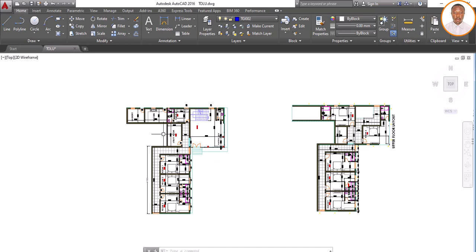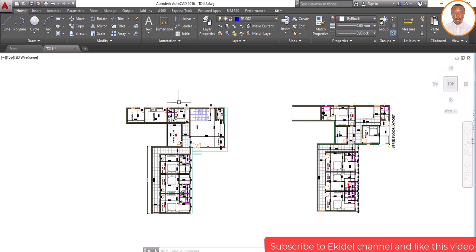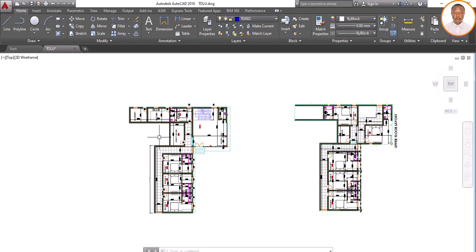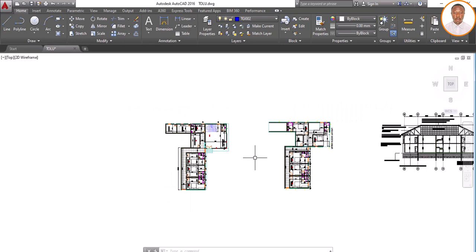The first thing, once the architect gives you a drawing, is to go through the drawing and understand it properly, so that by the time you start your GA, it will be easy for you. Don't just start your GA. First of all, study the drawing and view how it's going to be built in reality, and the kind of movement that is going to take place. Also identify which type of drawing you are getting from the architect: is it residential, hospital, or a school, etc. It's very important to study the drawing. So let's go and see how we can do the GA for this particular drawing.